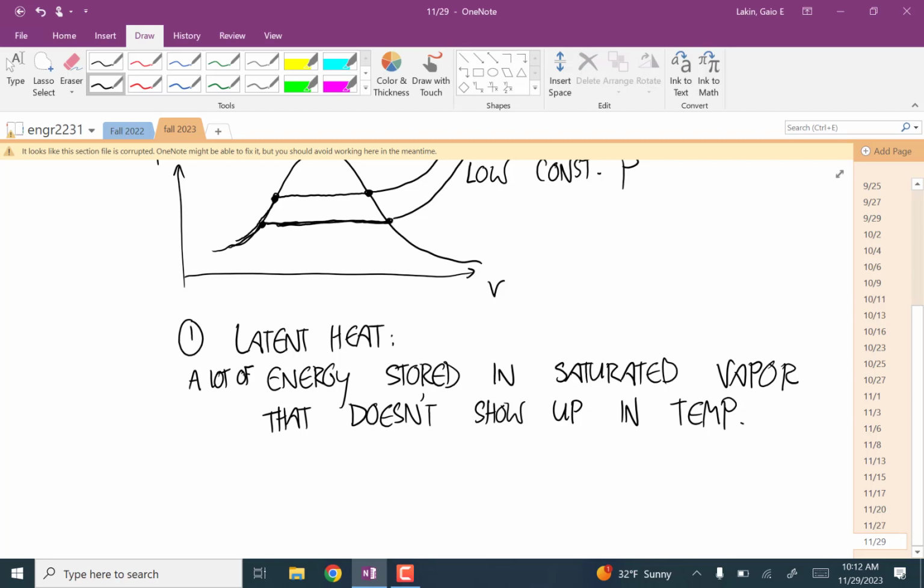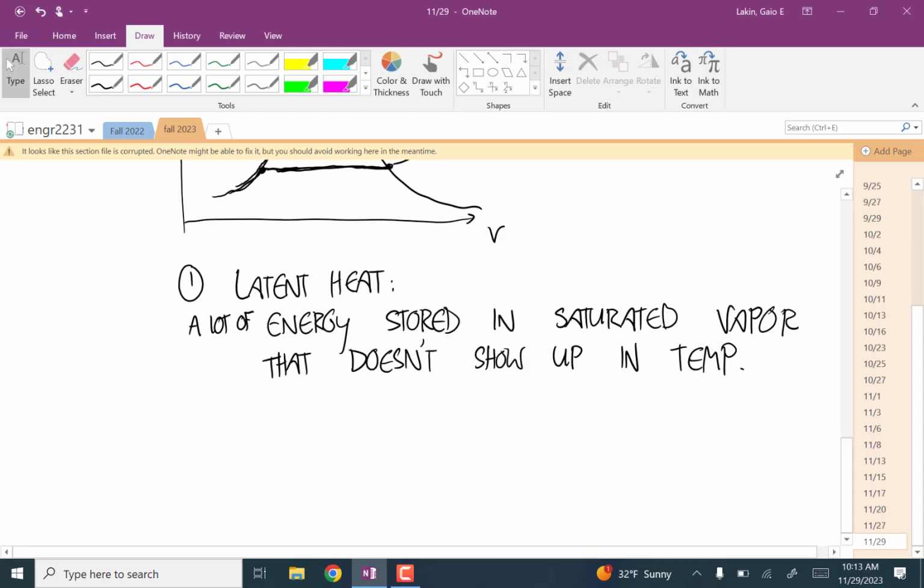Eventually the gas gets close to 500, and then no more is going to transfer. But if you have something that's 500 degrees, and a saturated liquid where the saturation temperature at that pressure is 300 degrees, now you can pour all that heat in, and it's stored as latent heat, but the temperature of the mixture isn't going up. So it's a much more efficient way to store and release energy. That's a key thing in engineering applications.